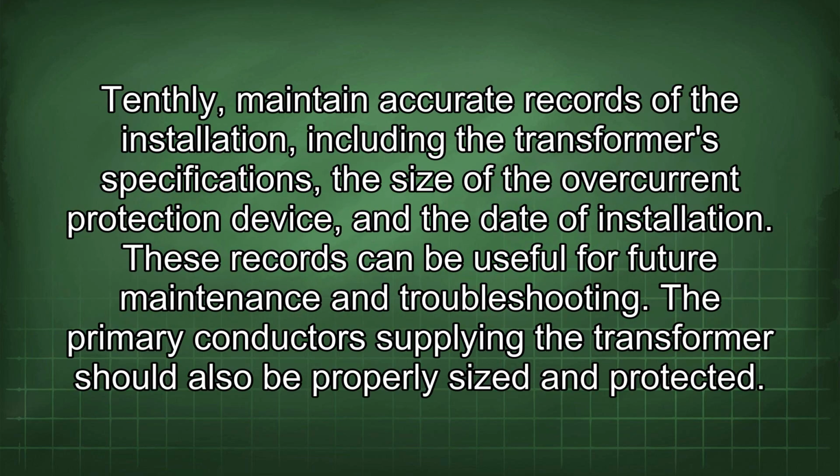Tenthly, maintain accurate records of the installation, including the transformer specifications, the size of the overcurrent protection device, and the date of installation. These records can be useful for future maintenance and troubleshooting.